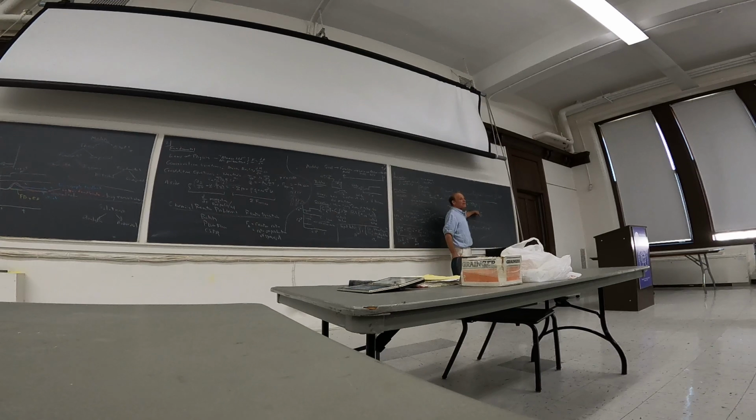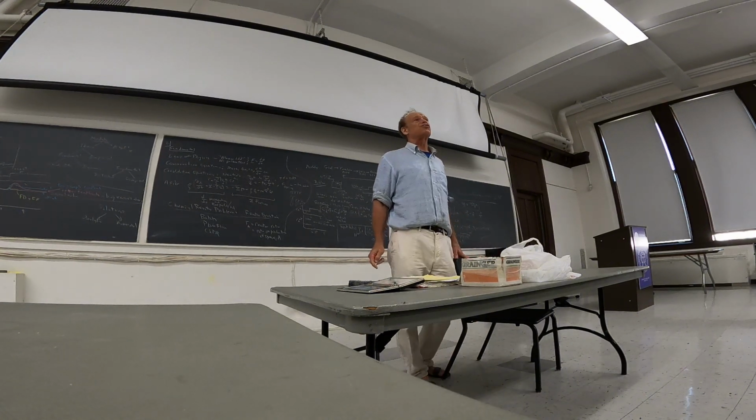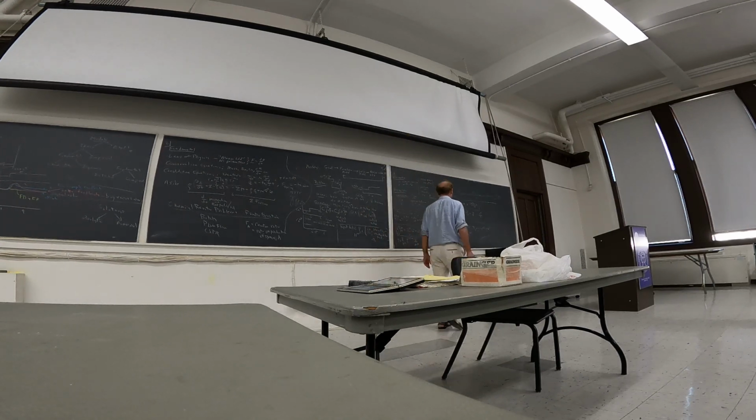Tau is a constant, CA in is a constant. CA is the variable. What kind of equation is this? This is a first order linear ordinary differential equation. It's linear because I have only CA to the first power or the zero power in every term. It's first order because I have only a first derivative.